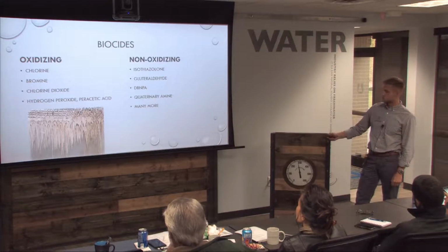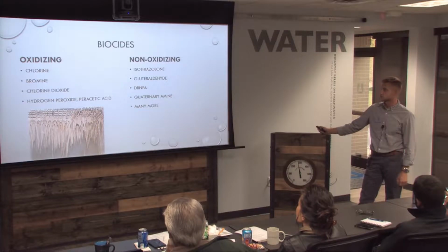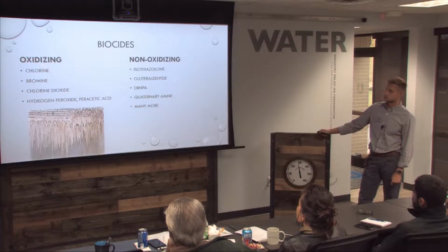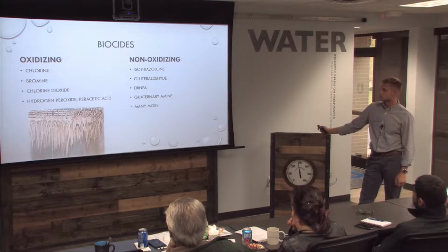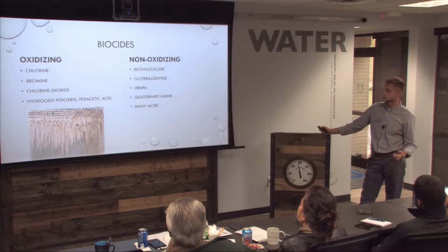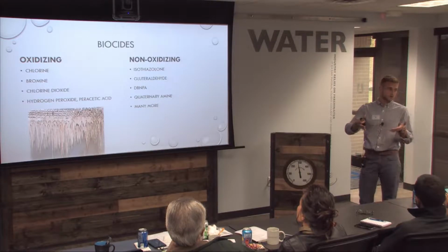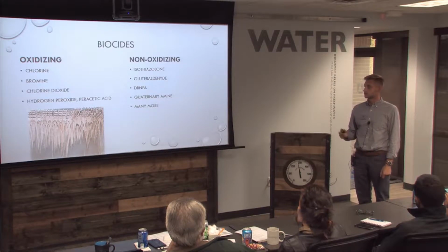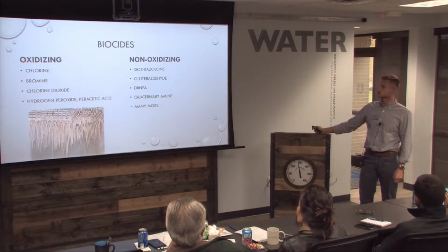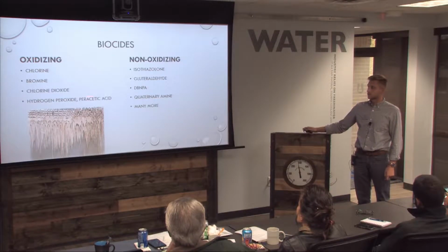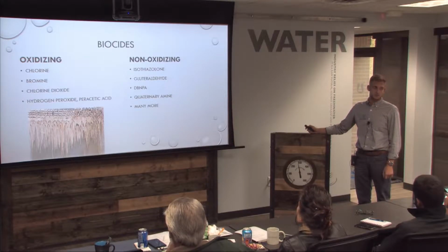But not typical. We see peroxide and peracetic acid, but they are options. We just outline them. You'll typically see these top two. And then we'll hit it with a non-oxidizing biocide, whether it be isothiazoline, glutaraldehyde, DBNPA, different amines. There's many more. Here's your bread and butter right here, again, based on pH. And these are much slower killing. Typically, you feed them, you hold the water in the tower for 30 minutes to an hour, make sure it is circulated, and then you'll dump. But those are fed in perfect tandem with the oxidizing biocides, just on an alternating basis.